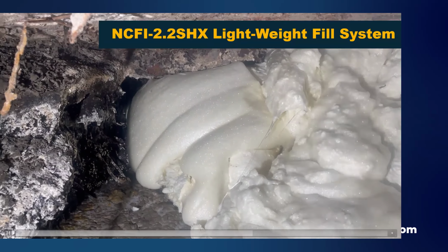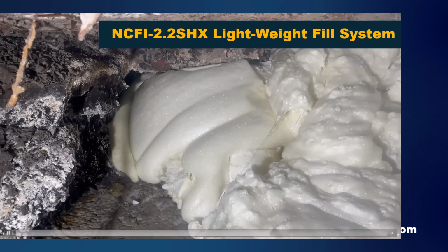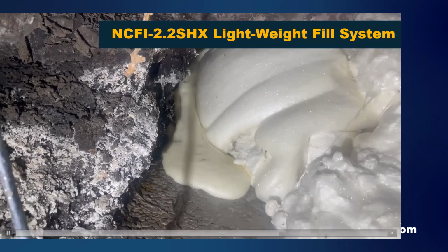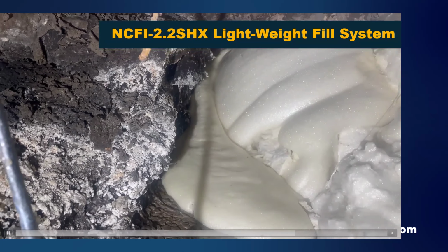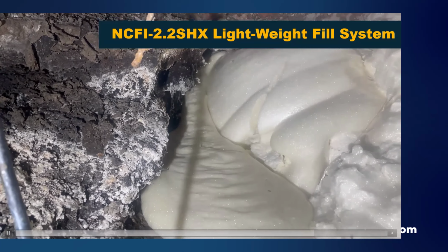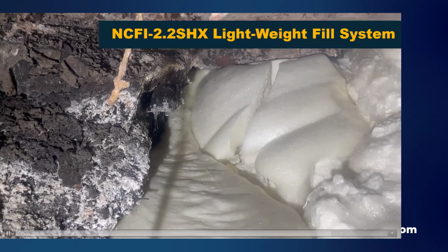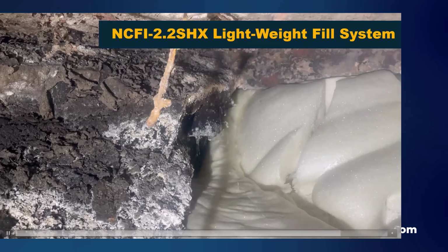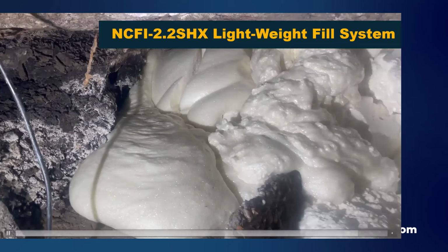Now, obviously, we don't always have the benefit of being able to see the entire void like this, where it's wide open. But with the use of, you know, drilling additional holes, and say if we were shooting this under a slab or something like that, you can drill some additional holes and use a camera to monitor, make sure you're getting consistent and good fill.